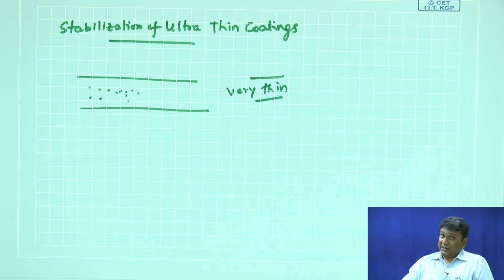non-wettable surface, and that is very attractive, because see, now with reduction of feature size, etc., in the electronic industry, you also have requirements for very thin resist layer for your photolithography, which we have also talked about, right, because in photolithography you also deal with a very thin film of photoresist, and you do not want any of these instabilities to manifest in the photoresist layer, because then your whole photolithography process will be spoiled.